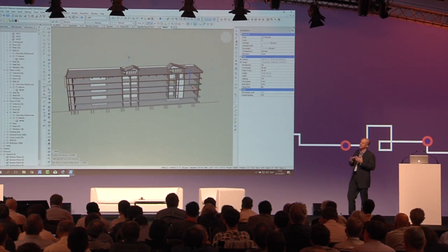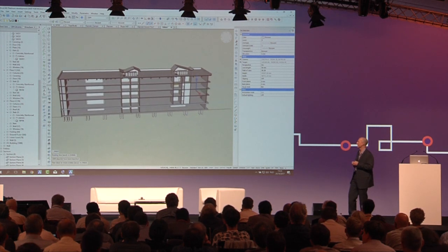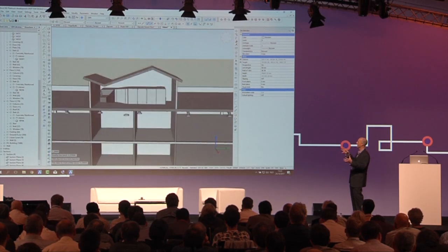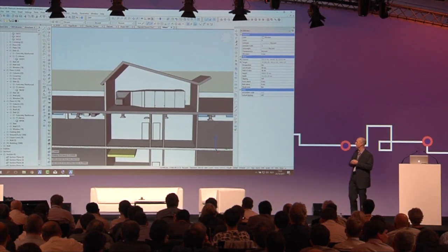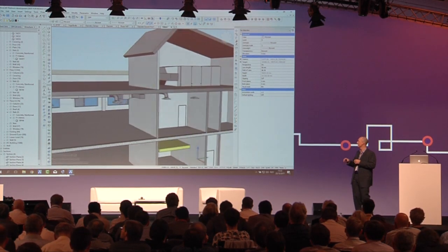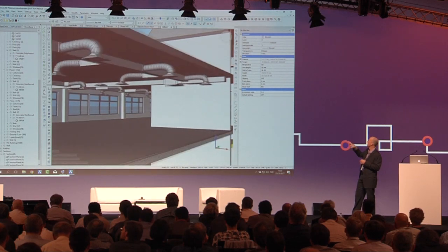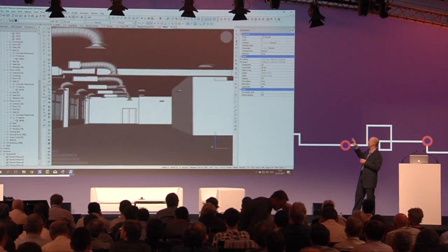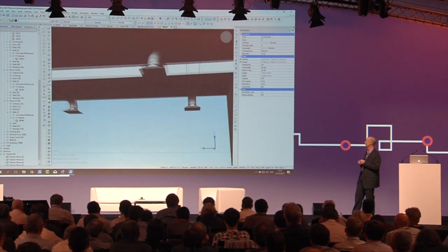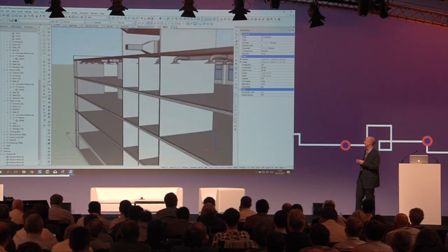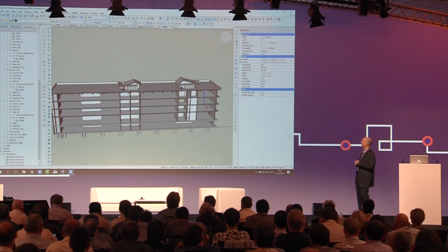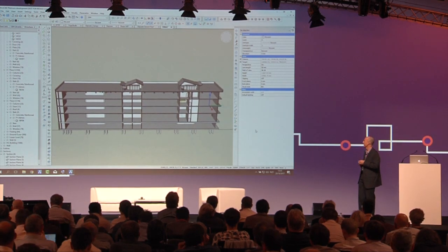Okay, so we can start to visually inspect it just to evaluate it initially. We see that there's some air handling units on the upper floor. Okay, they're inside the enclosures that we had initially laid out, so that's a positive. We can look at the supply air system layout. Okay, it's an overhead system, supply air diffusers, and some floating. There's obviously some conflicts with the returns that haven't been hooked up yet, so that's definitely something that we'll need to bring up in the meeting tomorrow. And it appears that they're assuming a suspended ceiling in that area.